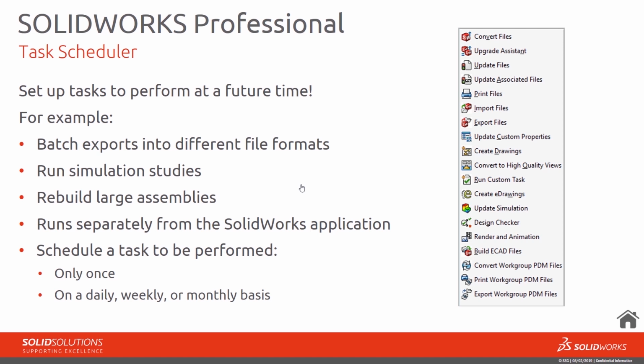We can also run simulation studies. So obviously they can take some time, so we can actually set it up, tee it up to solve overnight perhaps. We can also rebuild large assemblies. So if we've got huge assemblies that are taking some time to rebuild, we can actually say to SOLIDWORKS, look, do this just before I get in the morning, or maybe after work. What's nice is that it runs separately from SOLIDWORKS. So again, you can have this running on the side and still use SOLIDWORKS if you want to.